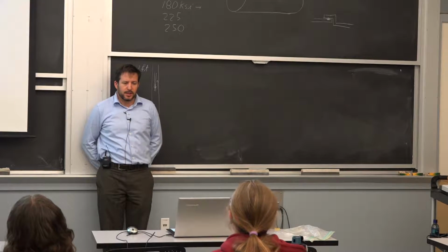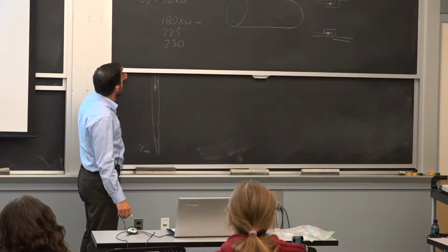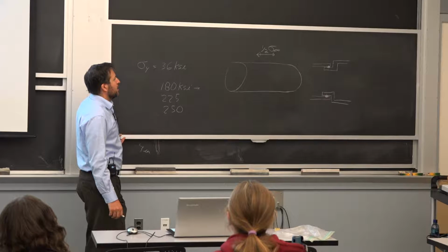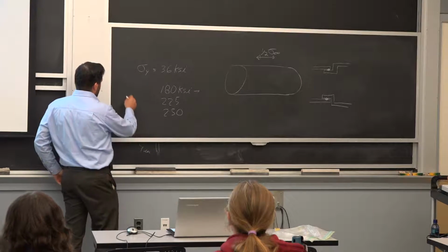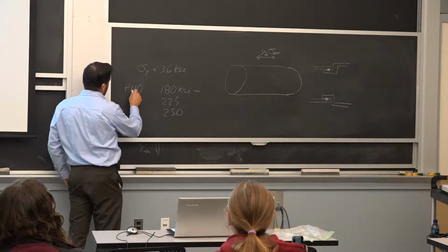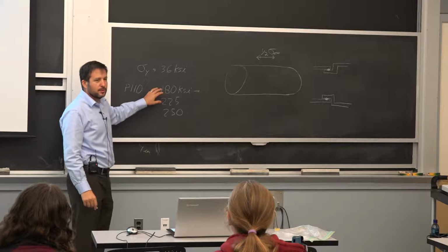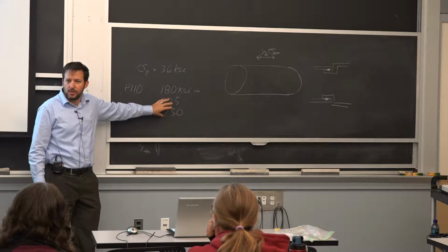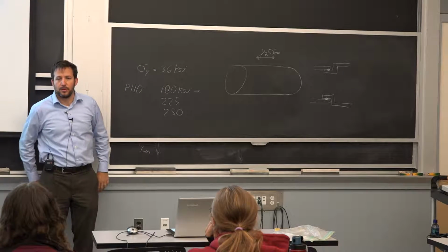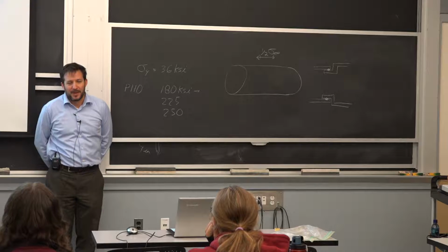What else did I say? So in the grand scheme of our strength here, P110 is a very typical drill string pipe. So 110 ksi is the strength. So you don't push it as much as you did with the wires, but you are about 3 times stronger than structural steel. Now, why are we limiting ourselves here?